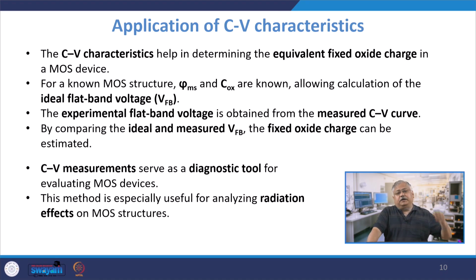So, what you do is that when radiation, for example a gamma radiation or an alpha radiation, falls onto the biased MOS device, it generates electron hole pairs, and because of the electric field, they tend to get settled in the oxide or interface trap charges. That changes the flat band and the threshold changes. Not only that, the CV characteristics will also shift. Shift means there will be a parallel shift either to the left or the right, right. There will be no enhancement or decrement in the capacitance because of radiation as such, but there will be a change in the threshold voltage of the CV characteristics.